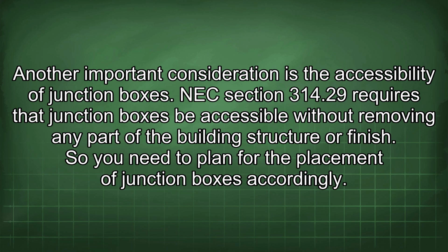Another important consideration is the accessibility of junction boxes. NEC Section 314.29 requires that junction boxes be accessible without removing any part of the building structure or finish. So you need to plan for the placement of junction boxes accordingly.